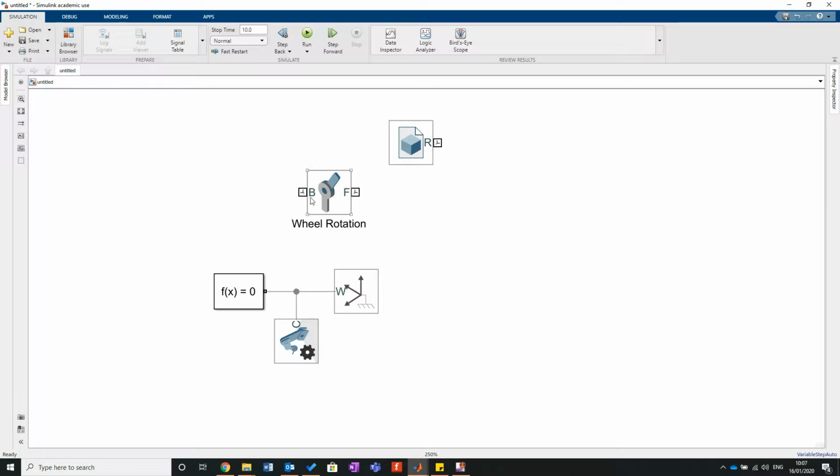So we have the base and we have the follower. The base describes its initial point where it's sitting, its housing, or the back, if you will. The follower refers to what's actually following within that state. In our case, it's the wheel. So I'm going to rotate this, Ctrl R, Ctrl R, Ctrl R, and snap that up. If that happens, it just means you made a mistake, so I'm going to do it again. That's better. Now we've got that connection.